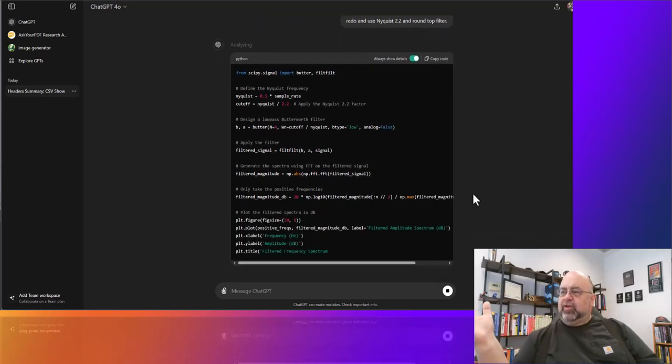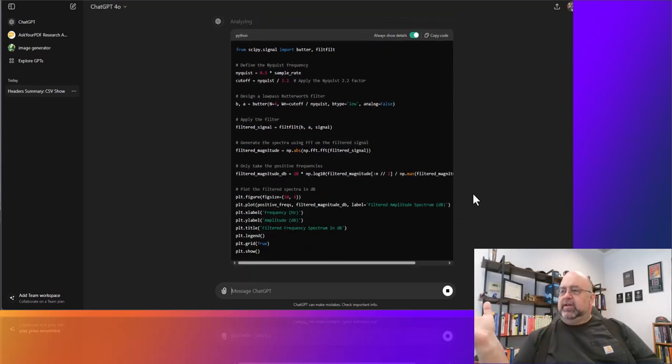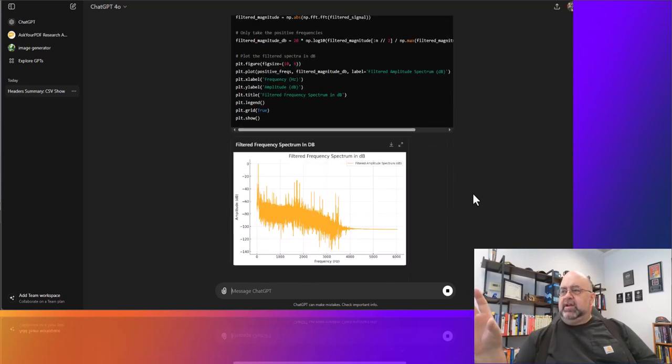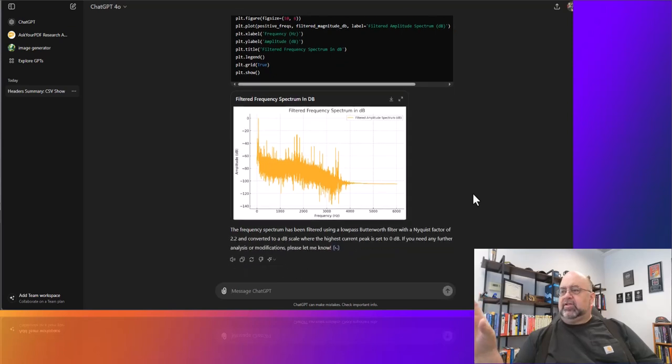Now, if I'm not sure what I want it to do, there's certain other things I can do as well. The other thing too, because it's not going to allow me to. There we go. Wow, it went out to 6 kilohertz, and I lost a lot there, didn't I? That's because of the Nyquist. So let's convert to Nyquist 2. Yeah, it used a low pass Butterworth filter. Don't use that. Okay. Nyquist 2.